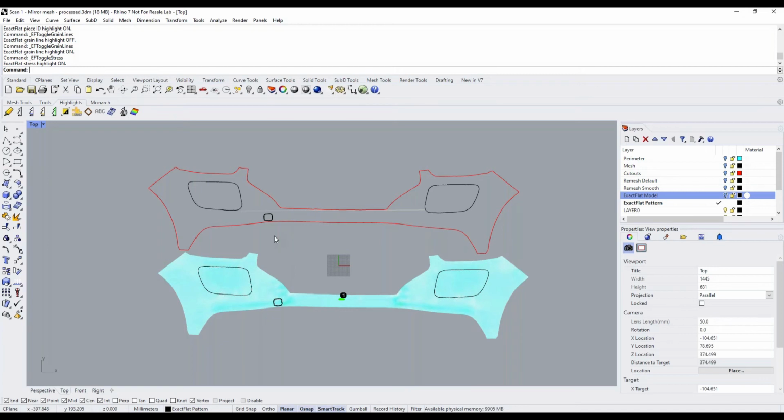You will develop your own scanning technique and you'll become better at scanning. As we mentioned, one of the big 5 best practices is scanning technique, where you orbit the scan surface approximately 30 centimeters away. You'll keep the scanner in constant motion, and with that constant motion, you will not overscan or underscan. You'll be sensitive to areas where there are pits or ridges, or areas where the bumper meets up with the quarter panel, for example, where there's a slight gap between surfaces. And you'll get better at it.